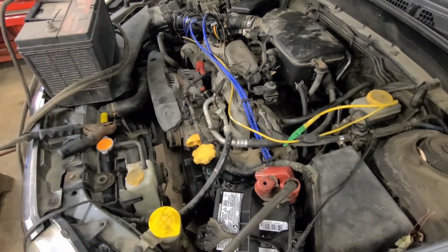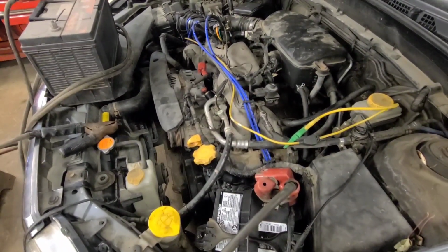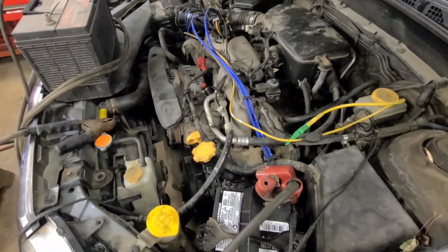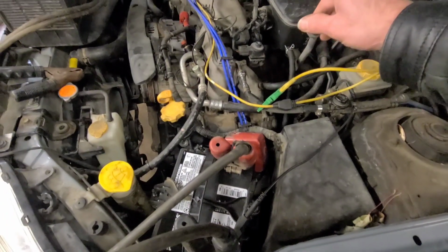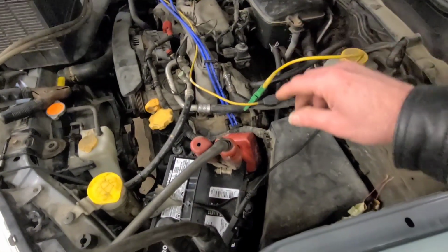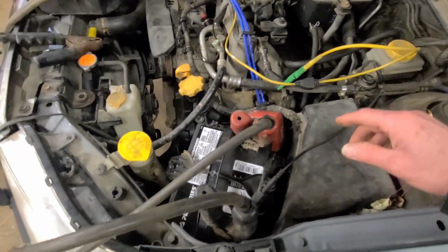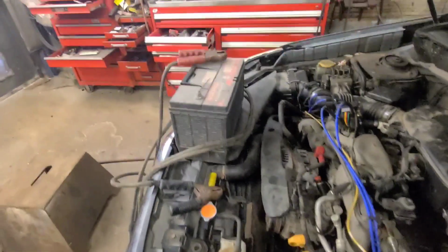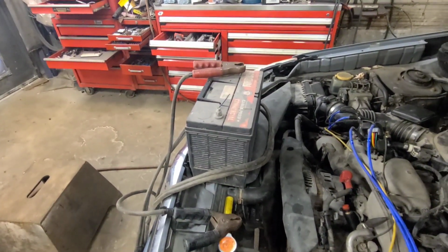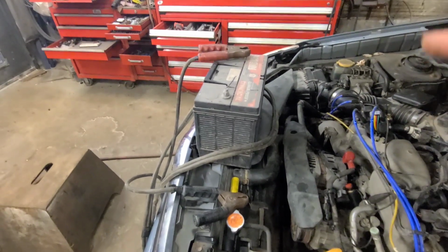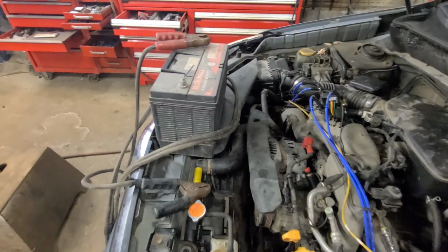So this afternoon I get home and I try to start it. It's warmed up to about minus 15 and it cranks, and I confirm there's no spark. So I've got these 2 jumper wires connected directly to the coil, power and ground, and I connected it right to the battery, and I cranked it, still no spark. So then I connected these 2 wires to an auxiliary battery that I just took off a charger in the shop that's probably at about 13.5 volts, and I still got no spark, and it doesn't run.